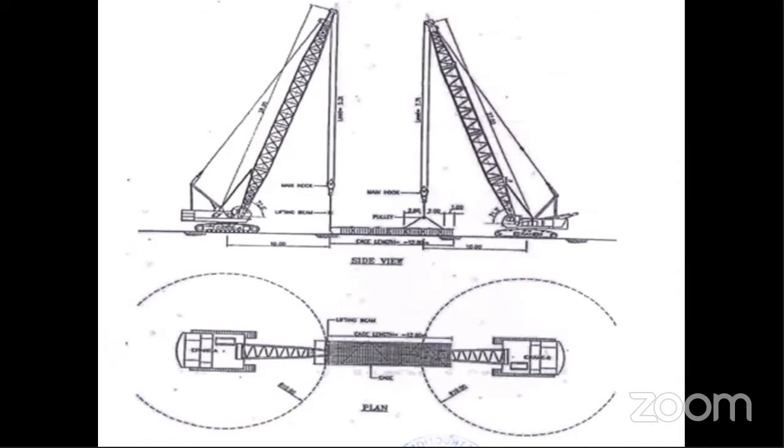The reinforcement cage should be fabricated according to the good for construction drawing only, based on site conditions or the availability of equipment. The reinforcement will be placed so that it does not touch the trench, because once it touches, it is going to cause the soil to collapse.